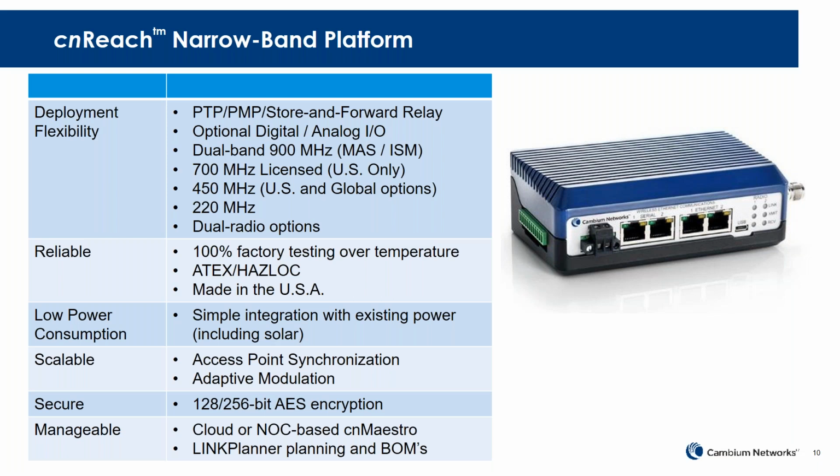We do test every single radio over temperature. So each radio is tested up to and functionally performs at 85C. So this is 100% testing to 85C. That's unique in the industry as well. The locations where these radios go can often be very hot areas, both because of the temperature in the environment, but also because of the machinery that they're operating around. So the temperature rating on this is higher than the other products in the Cambium portfolio.